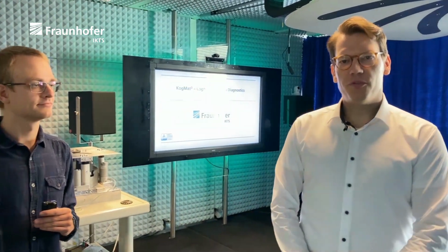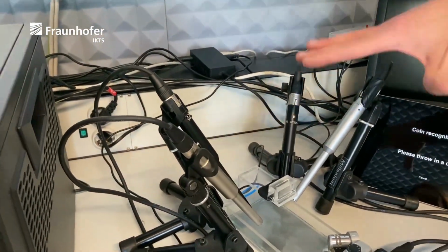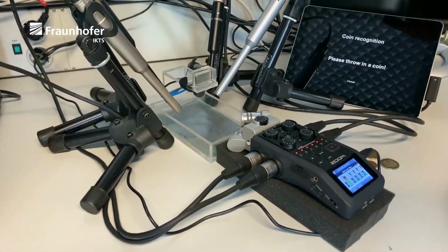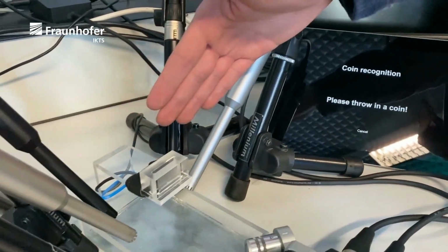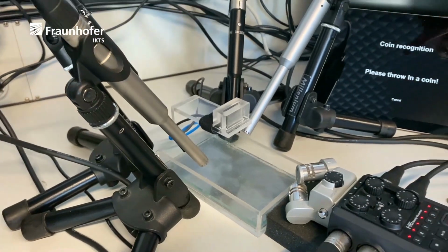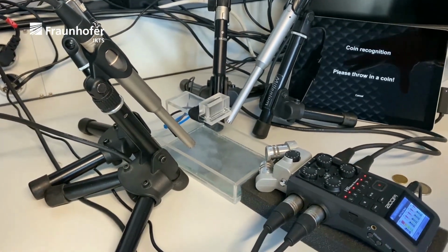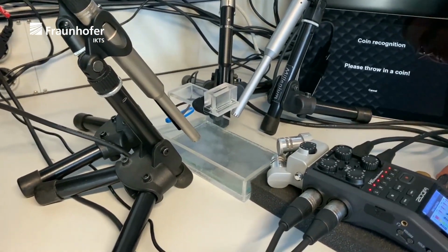The first demonstration will be given by my colleague Dario, and the demonstrator will adequately show the possibilities of machine learning. Thank you, Sebastian. The demonstrator consists of a tray and the microphones arranged around it. The microphones are connected with a Surface Go, which does the classification work. When the coin is dropped, the impact noise on the rippled glass surface is recognized by neural networks for each microphone channel separately and is then combined for the best recognition rate.